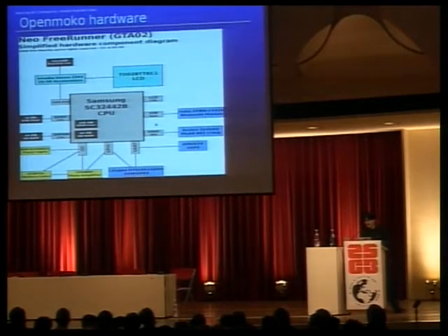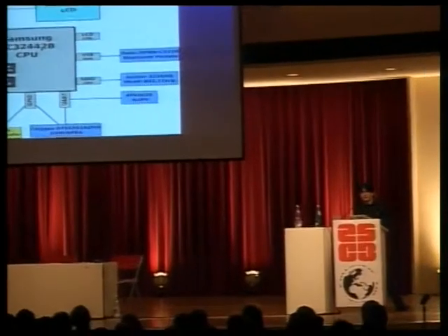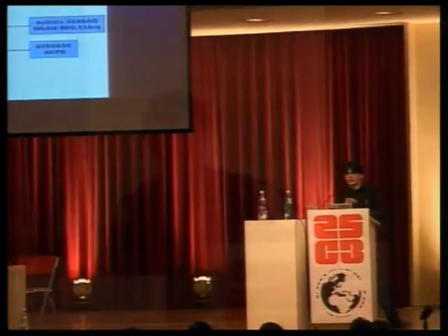So this particular component is one component that is 13 by 13 millimeters, and I think maybe 1 millimeter in height. I don't remember exactly. And in that single package, there is not only the system on a chip, but also the flash and RAM memory. It's what's called a multi-chip package. So you have multiple dies inside one physical package to save what's called PCB footprint. So you save space on your board design.